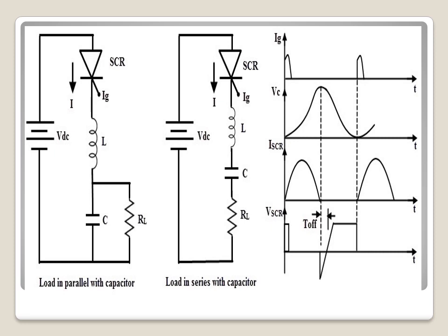This means the commutating components make the current through the load zero and this commutates the thyristor. This signifies that unlike turning on the SCR, where the gate terminal acts as a direct switch, in turn-off no direct switch exists, and so with the use of external components the device is commutated.